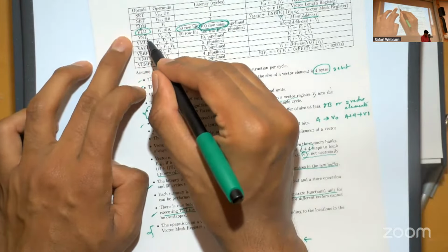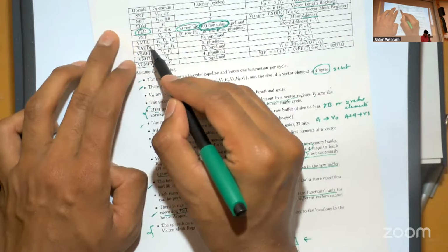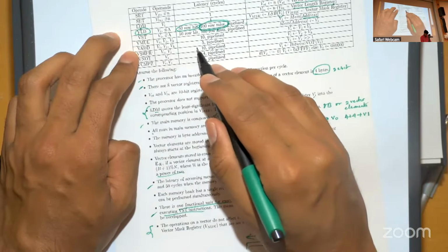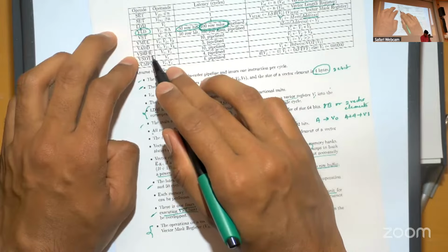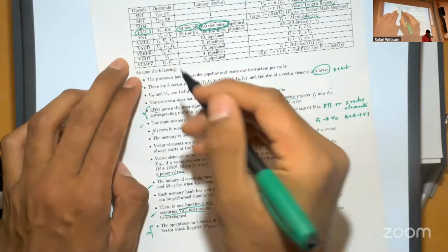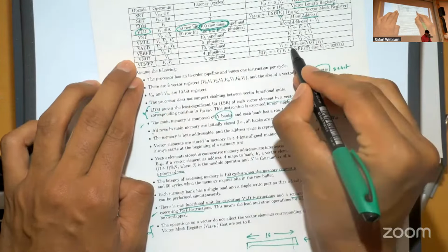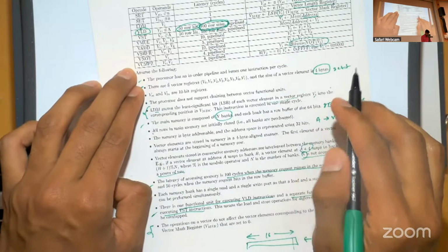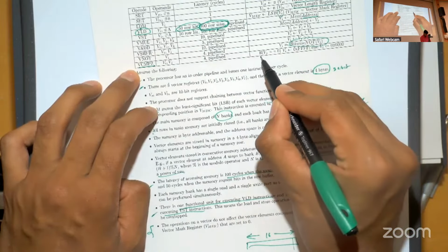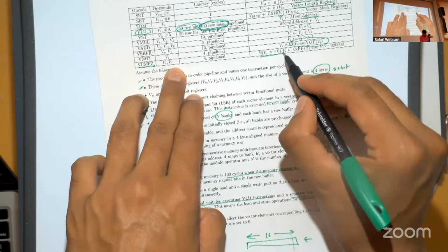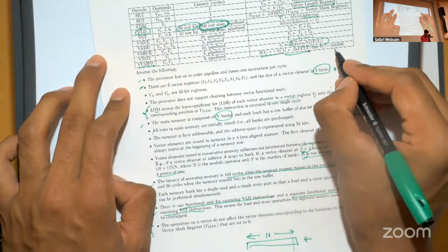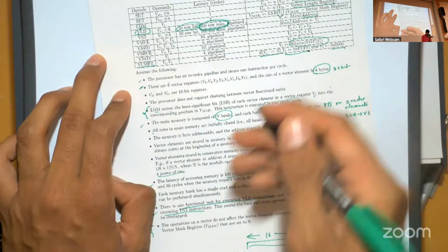We have already seen VLD and VST. We have VMUL, which takes 10 cycles to perform multiplication. It's pipelined. We add 5 cycles pipelined. We shift right. You can shift right by 1. And then you have VNOT. It performs the bitwise NOT of VI and restores it back into VI. And then you have the V compare if 0. If you compare VJ to 0, and if it is 0, VI will be stored with all ones or all zeros. It's to compare if the values are zeros or ones.